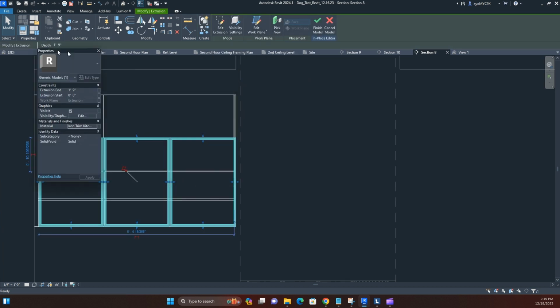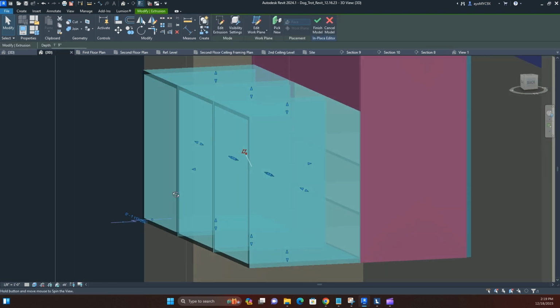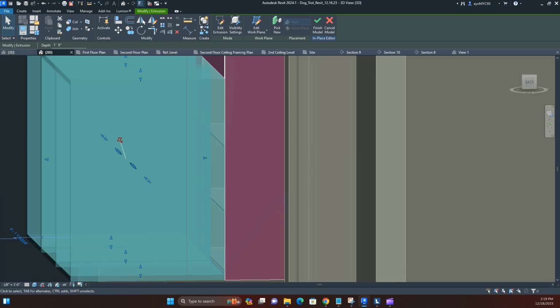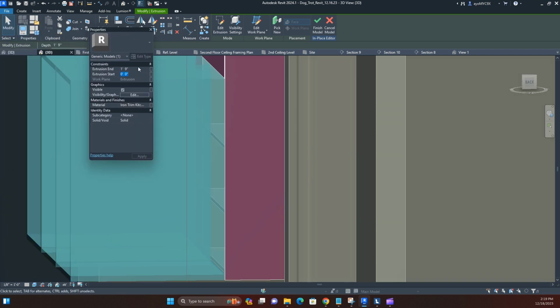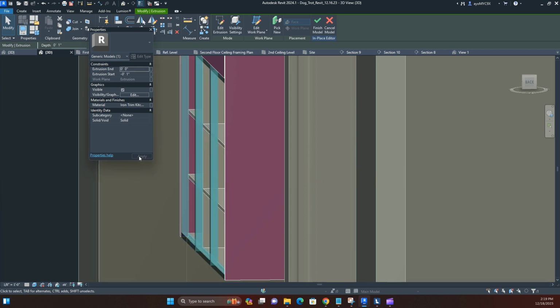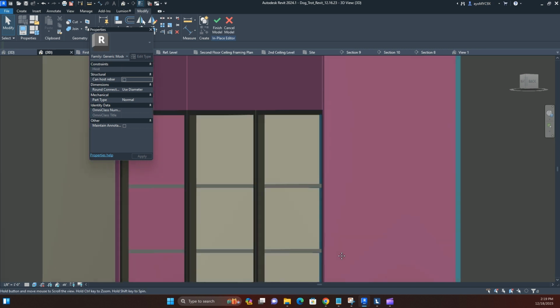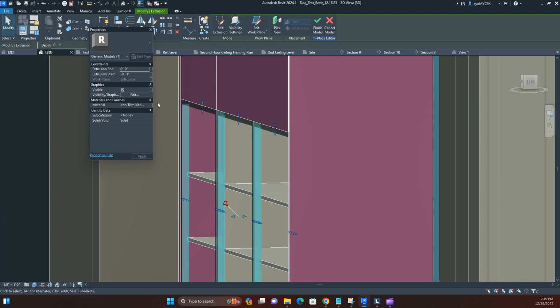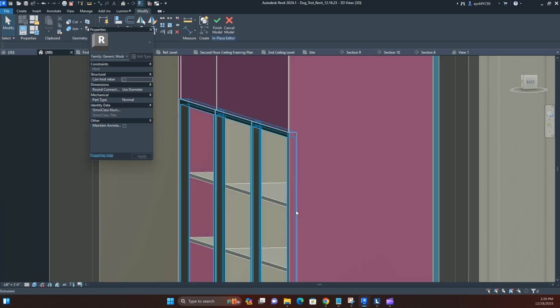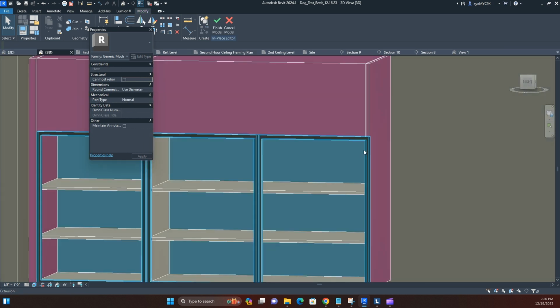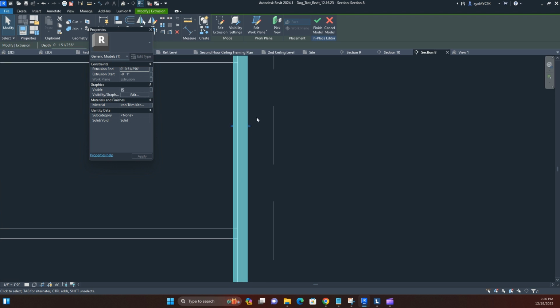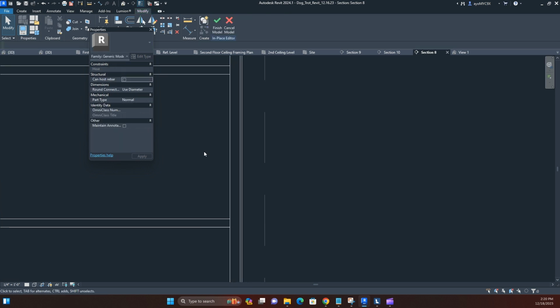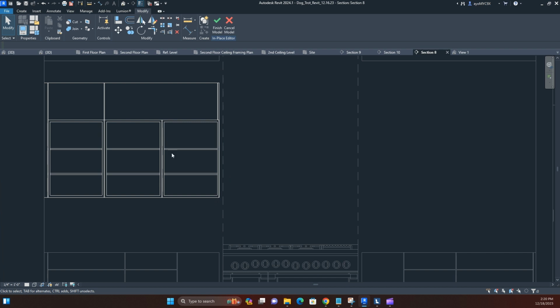We'll finish it off. Let's take a look at it in 3D, see what we're working with. Okay, there we go. So we need to nudge it back in place. Instead of extrusion, start at -1 inch and it should end at 0 inch. So that gives you 1 inch thickness, right? If you want it shorter, you could adjust it to whatever your need is. But hey, this is your life. You could do whatever you want with it. Then 0.2 to nudge off past the wall cab a little bit. Then let's take this out a little bit so the overlapping doesn't mess with the height while we do our rendering.